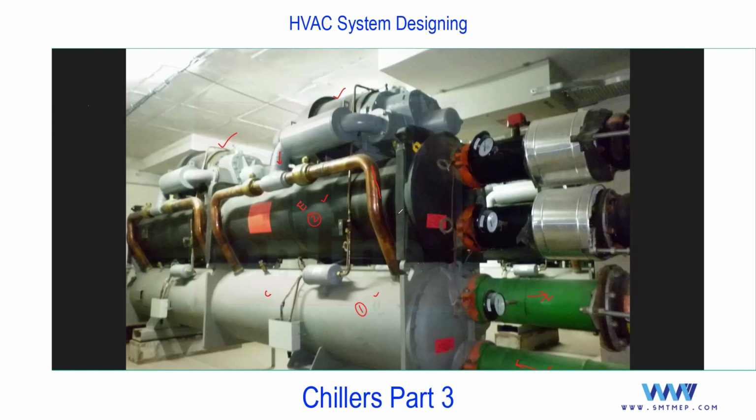So you'll find two shell and tube heat exchangers, and because of this, you'll find three cycles. One cycle is what? The vapor compression cycle. Same: compression, condenser, evaporator, expansion, you know all this. The second cycle is the chill water cycle, same as air cooled. And the additional cycle in this is what? The condenser cycle, which will connect to the cooling tower with a separate pump. And why the need of this cooling tower, and how to cool the water which is used to cool the refrigerant, that I'll show you with the line diagram.